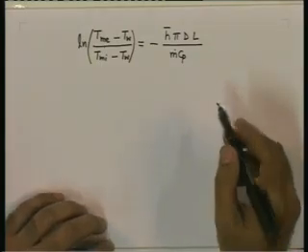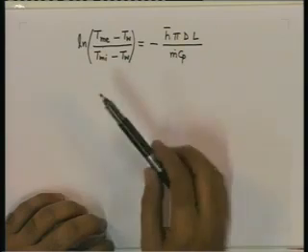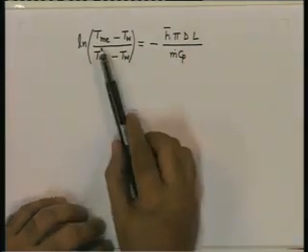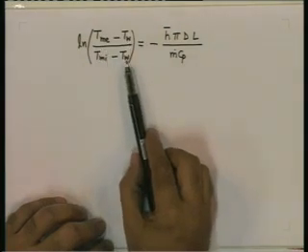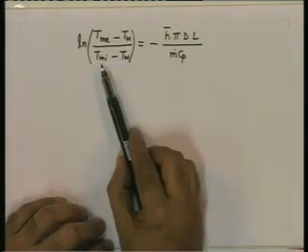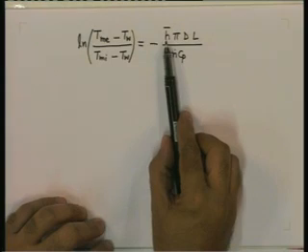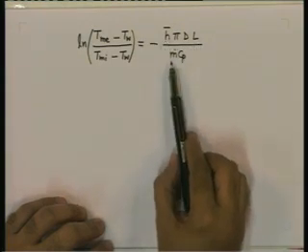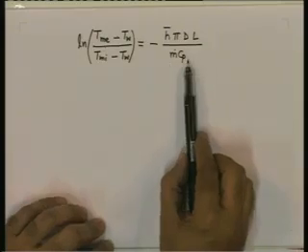Now notice that in this expression we have the values of everything except Tme. Wall temperature is known, inlet temperature of the fluid is known, heat transfer coefficient has been calculated, D, L, m dot are specified, Cp has been determined.